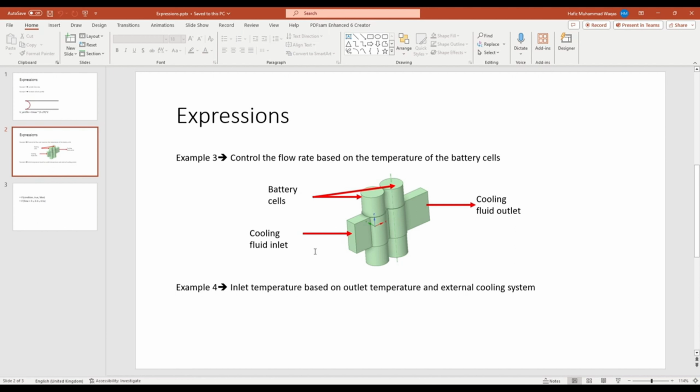First things first, whenever you're writing an expression, always start by writing a rough algorithm in a text file or on a notepad. It will give you an idea how your expression will be constructed and how you are going to implement it in Fluent.